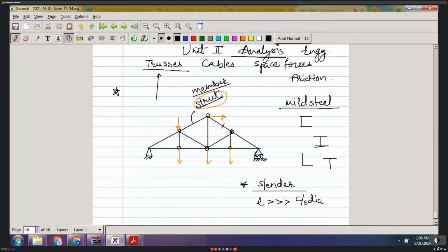Prevent the sag. Whatever loads will act on these joints, because of that all these members will have tendency to have either compression or tension in them, and to overcome these stresses developed in these members, we always keep one support as roller support, so that it will have its motion freely along that plane on which the roller is resting, so that there will not be any generation of stresses, and ultimately your entire structure will remain in equilibrium. Is it clear?